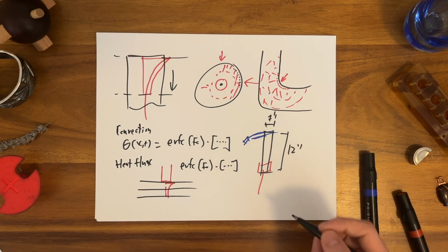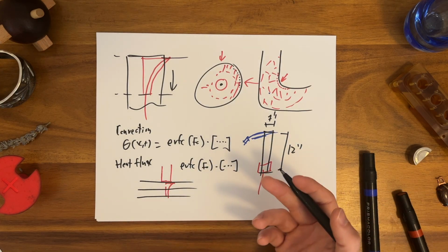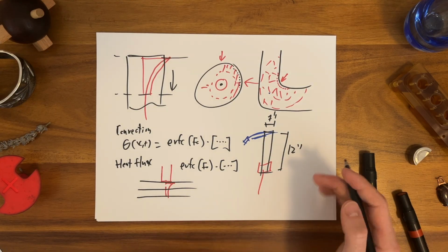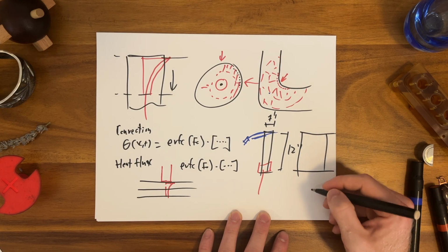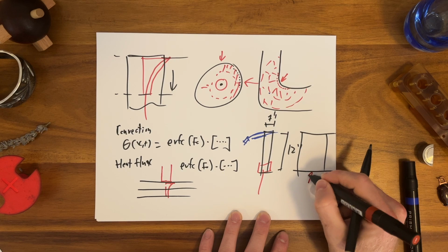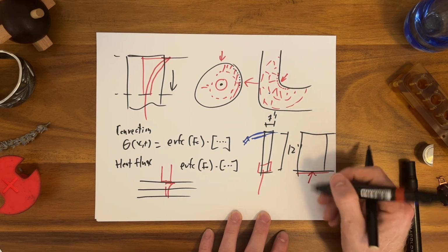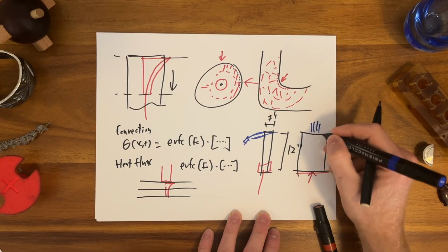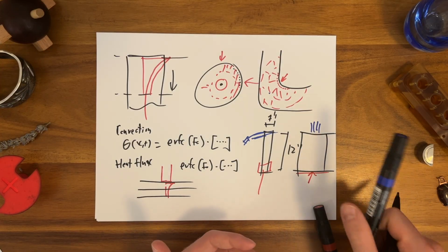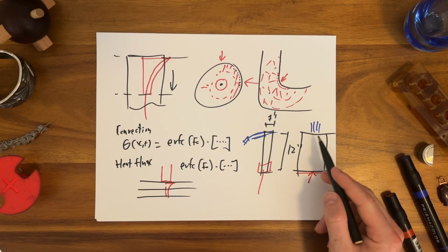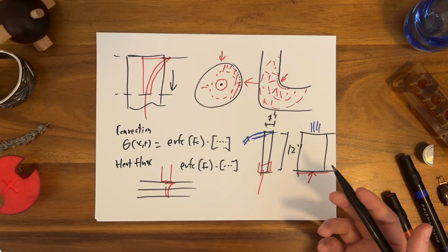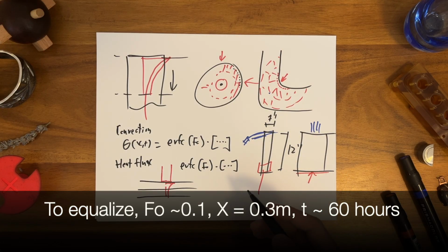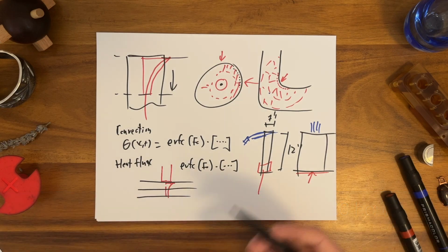And this really freaks people out because it's a really small rod. The heat capacity is low. You think you could really heat it up pretty quickly. The way to think about this is imagine there's a giant wall of steel and you're on the inside and you put your hand on the inside of the 12-inch thick wall of steel, and someone else has put a torch on the outside. How long can you put your hand against the wall? You can keep it there for a long, long time. And this is also an issue if you're heat treating or welding steel and you have giant weldments. It might take hours to days to slowly preheat or post-heat your material, just because steel doesn't move heat that well.